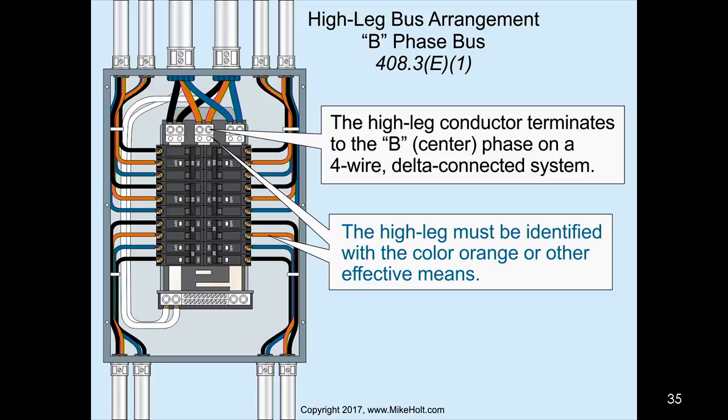So be careful that you might go to some application, like Brian, like, they put this sucker in the wrong phase. Well, I'm here. Let me clean up the panel board, fix it all up. I'll move that baby from the C phase to the B phase, because you're pulling out the guts in that panel. You're going to replace that thing, you're going to clean it all up. And all of a sudden, you don't realize there's a reason that it was that way, and that was the system at that time, back in the 70s.